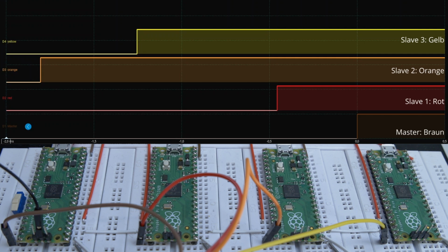The Picos are freshly powered up, and the logic analyzer shows all of them flashing their LEDs inside a 2 millisecond window relative to each other. The leftmost brown switching its LED acts as the trigger point, and it will become the sync master once the drift estimation is turned on. All other Picos can be seen drifting to the right at different rates.